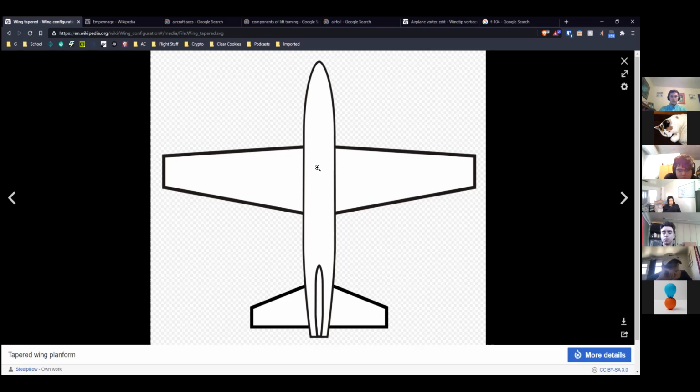And so the thickness will vary with the chord. If you have a bigger chord, the wing will be thicker here than it will be at the tip, which means you can stuff more structure into the wing here where you need it, because here the wing is supporting all of this, whereas here that part of the structure is only supporting this stuff.